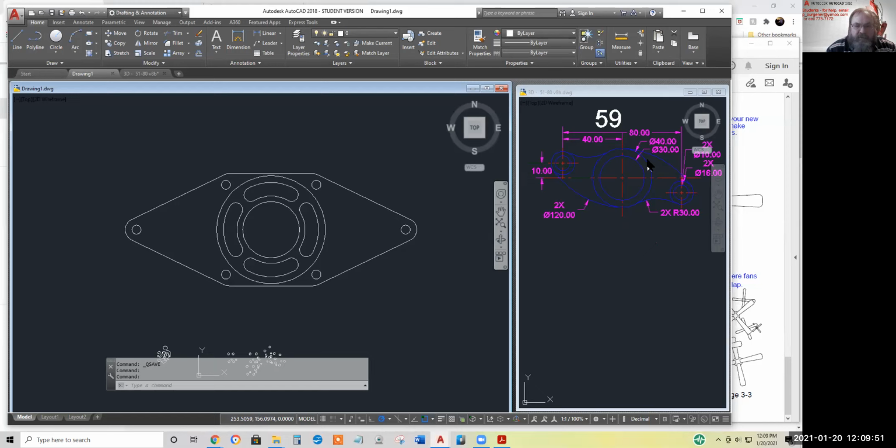The tricky part of this one is that after you've completed one side, you can't simply mirror it across. If you did, the thing would be kind of boomerang shaped. So you need to mirror this after completing one side, mirror it down here, then mirror it across, then snap it and move it into position. So it kind of takes a double mirroring to get this. It is a very popular exercise, by the way.